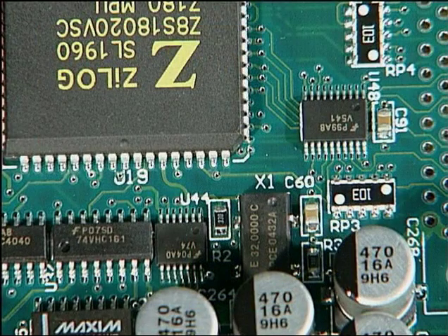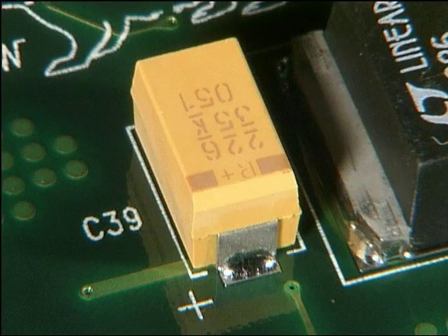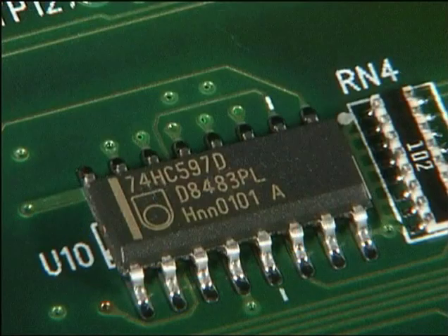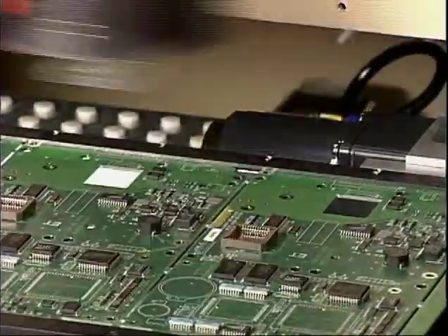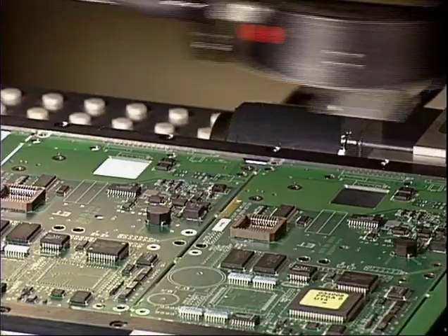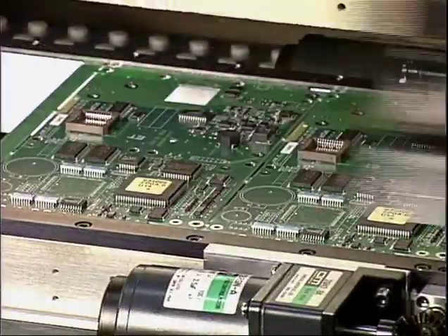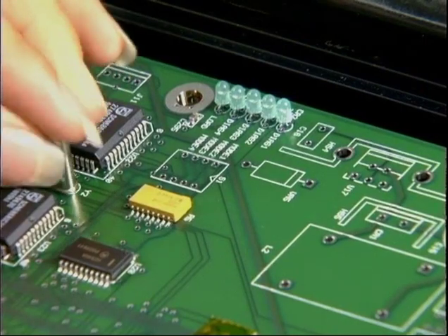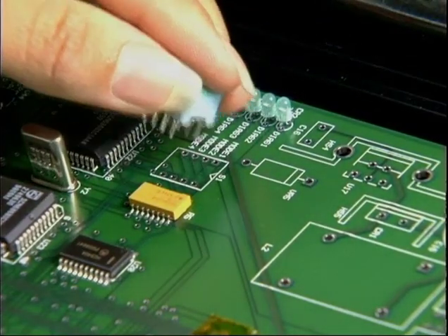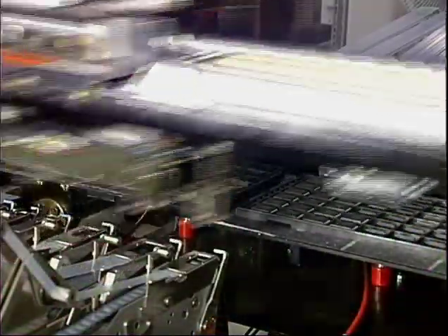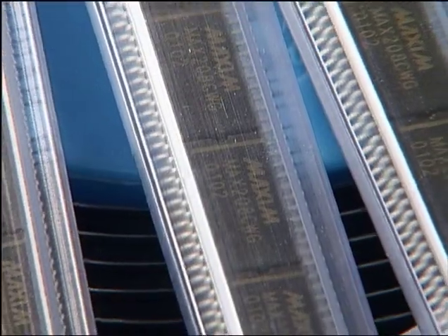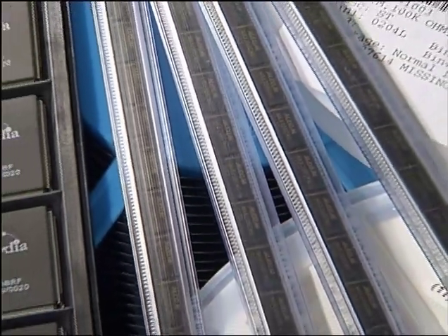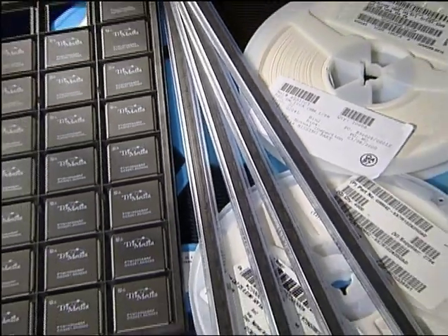Surface mount devices use the same system of part numbers, reference designators, and component values and tolerances as through-hole components. And the indicators for polarity and pin 1 orientation are also similar. What's different is that surface mount assembly is more compatible with automated processes than through-hole assembly. Because of their size and shape, many types of through-hole components require manual insertion. Almost all surface mount components can be placed by machine. The components come packaged from the manufacturer in one of 3 forms: on tape and reel, in tubes, or in waffle trays.